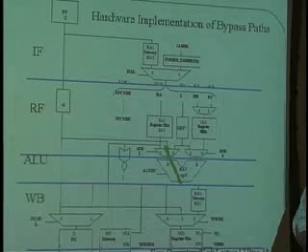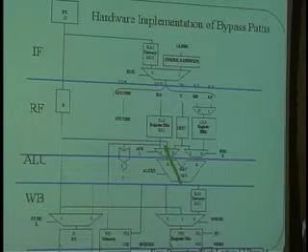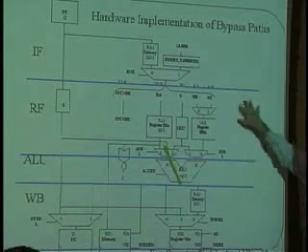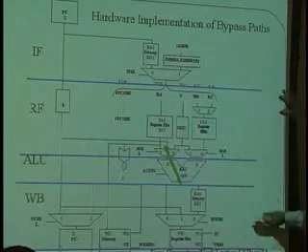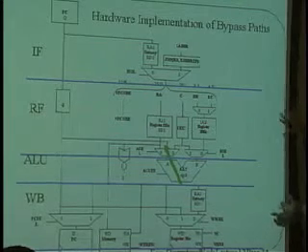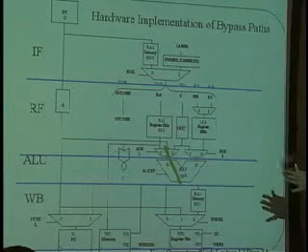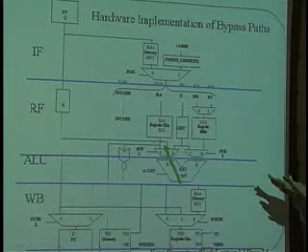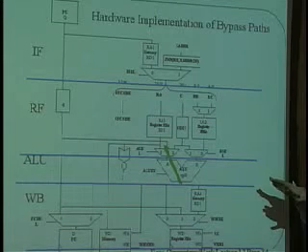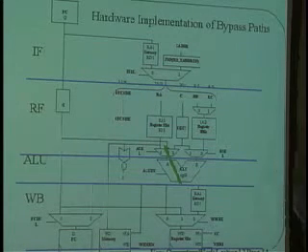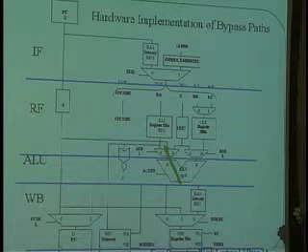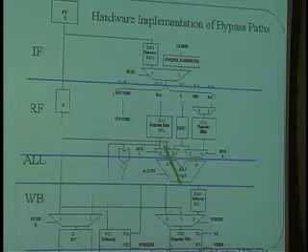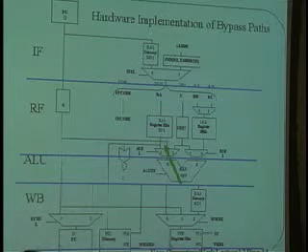To do that, we need a way of comparing RC and the old instruction. You betcha. So we're going to take all this stuff and we're going to time delay it in different things. We're going to have a big, hairy piece of logic that's going to sit there and look at this dance card all the time and figure out how to move the multiplexers for the bypass paths, or if things get really jammed up, how to insert no ops into the machine, a bubble into the machine to slow things down. Is that going to be done in ROM, or would that be done in... It'll be done in logic. No, it's actually going to be some and/or type logic.